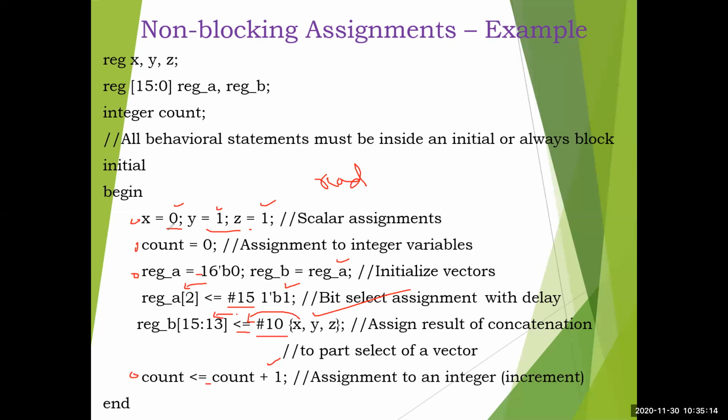Whereas here blocking statements are used, so these will execute in order, up to here. The non-blocking one will not wait; it will execute at time 0. These others will execute at 10 and 15. Hope it is clear somewhat.